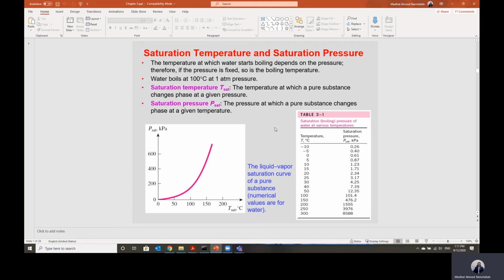And this is the idea, Shabab, of the pressurized cooking vessel. The idea is to increase the pressure, and then the boiling temperature of the food is raised. Usually most of the food is water, so any food will be boiling very close to 100 degrees C. So if I raise the pressure inside this pressurized cooking vessel, the temperature at which the boiling occurs will be raised.